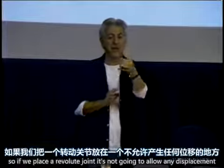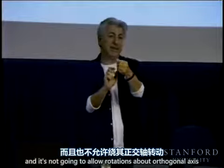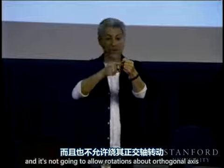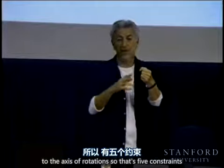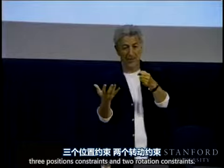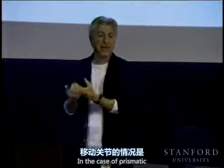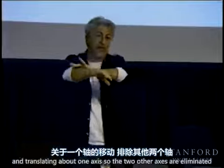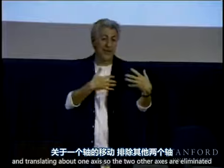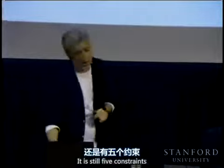If we place a revolute joint, it's not going to allow any displacement, and it's not going to allow rotations about axes orthogonal to the axis of rotation. So that's 5 constraints: 3 position constraints and 2 rotation constraints. In the case of a prismatic joint, it is not going to allow any rotation. It's just translating about 1 axis, so the 2 other axes are eliminated. It doesn't matter. It is still 5 constraints.